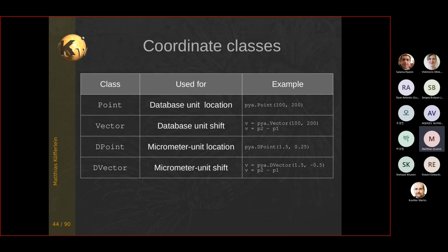Yeah, I mean, that's easier. First of all, these objects are quite simple. So these are two numbers simply. So there can be anything like kilometers or whatever, right? But it's a convention inside KLayout. If you use these points, for example, to generate a polygon or path from, then you mean this is micrometers. And KLayout knows that when it writes these objects to GDS, it has to compute the actual dimension by dividing by the database unit.